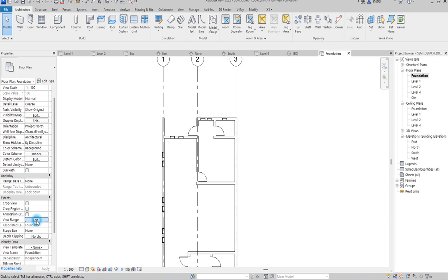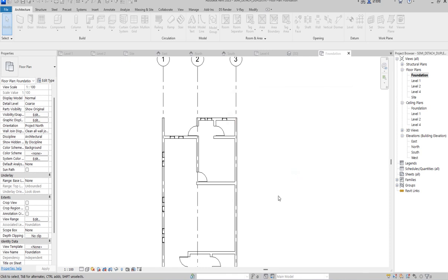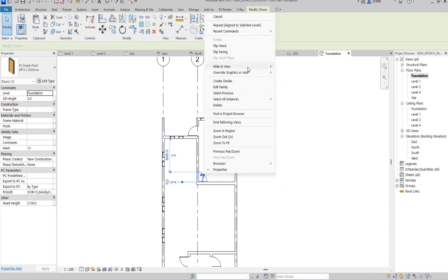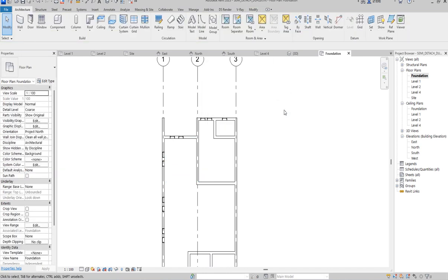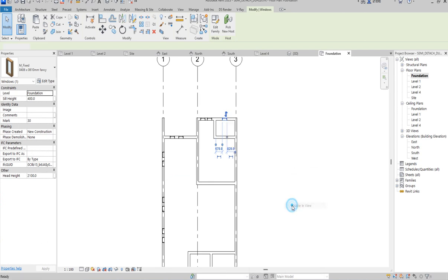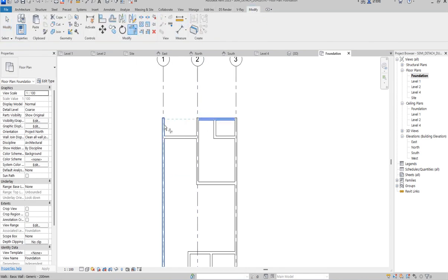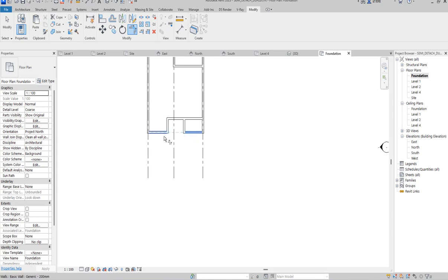So you can just edit it again. Here this time around, I'm going to say not 700. I'm going to cut it from 500. Then I will do the offset by 450. So I say okay and okay, good. So select here and say select all instance in this view. Select all instance in this view and you say delete. The same thing here, select all instance in this view and you say delete. So this time around now you connect everything together, then fix them.